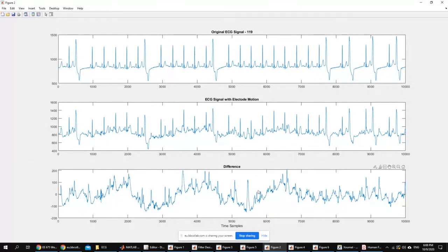This is the noise. It definitely has a baseline wander component, but it also has an overlapping high frequency component. So for this particular type, you will probably need to apply both filters, low pass and high pass, which means that you effectively will have to use a band pass filter.